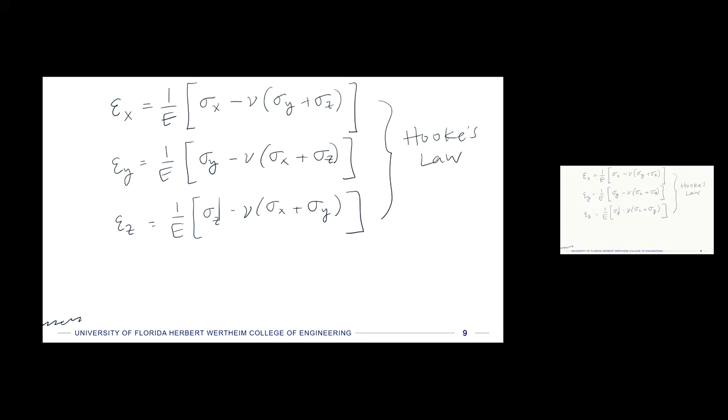Okay, so we talked in the prior lecture about principal stresses. And so now we're going to also talk about principal strains that go along with that, right? So these expressions that I've written up here are in terms of x, y, and z, right? If we wanted to calculate the principal stresses, we could do that. And they actually relate similarly to the principal strains, okay? If we said that for any given situation, this XYZ coordinate system is our principal coordinate system. Let's just say that we solved it and XYZ is equal to 1, 2, and 3 in this case.